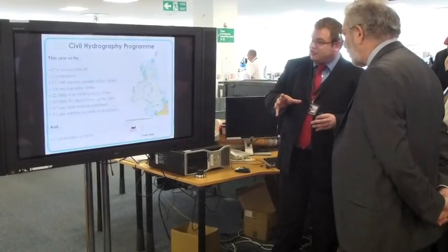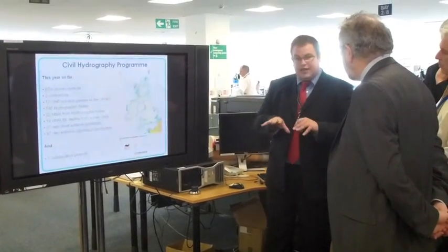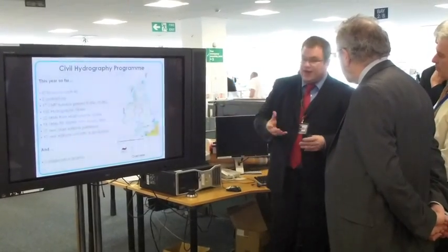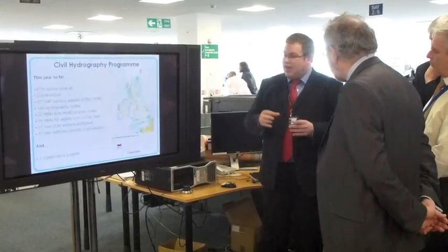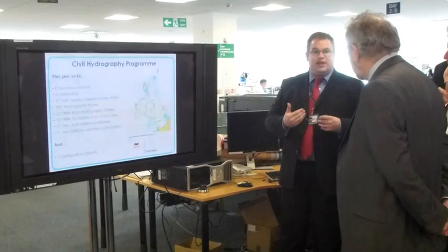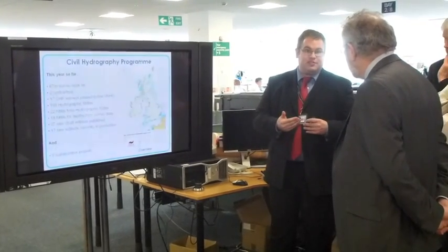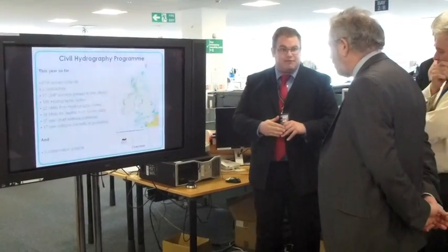And what it also allows us to ensure is that we're seeing everything that's on the seabed, because these systems typically are just interested in the seabed itself. But Order 1A allows us to actually make sure that we're finding all of the wrecks and features, man-made objects that have been left on the seabed, so that gives us the confidence we need to make sure that charts are fit for purpose for mariners, especially for the objects that are standing proud of the seabed, for example.